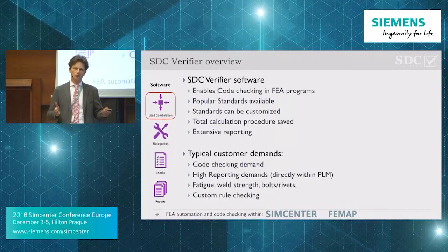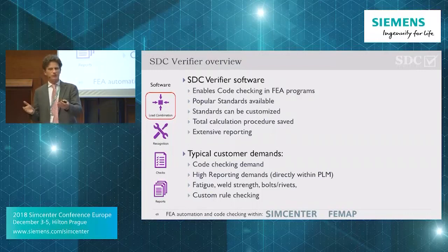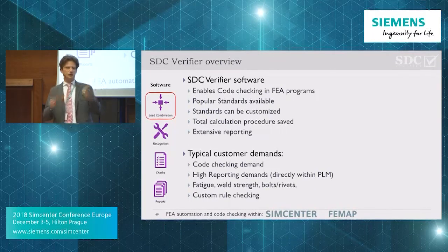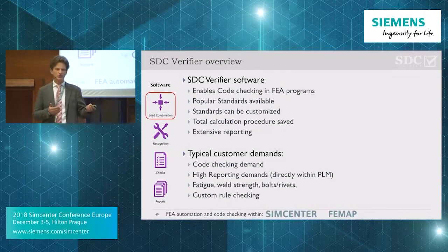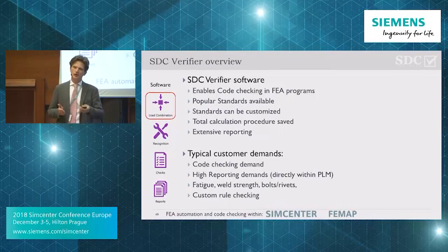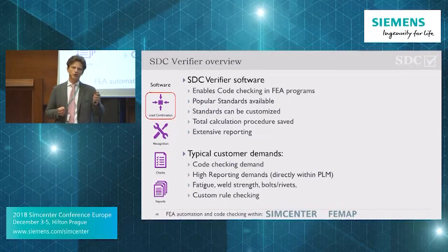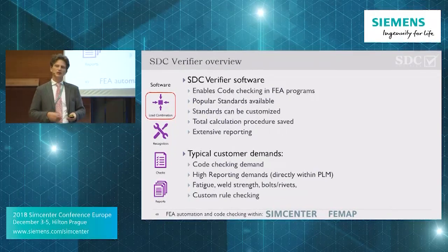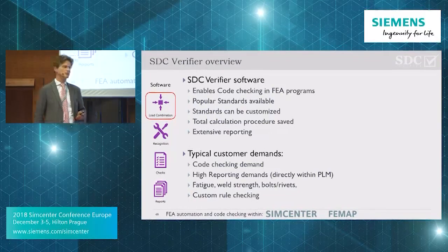You can not only update the reports, which is the simple step, but you can also use valuable info like weight of components, stresses, maximum stresses of components, utilization factors on fatigue or maximum fatigue life, and assign that to components so somebody else can see, okay, for a component I directly have the overview of what has been done by this analysis and what the results are, without opening anything and directly having the right info available.